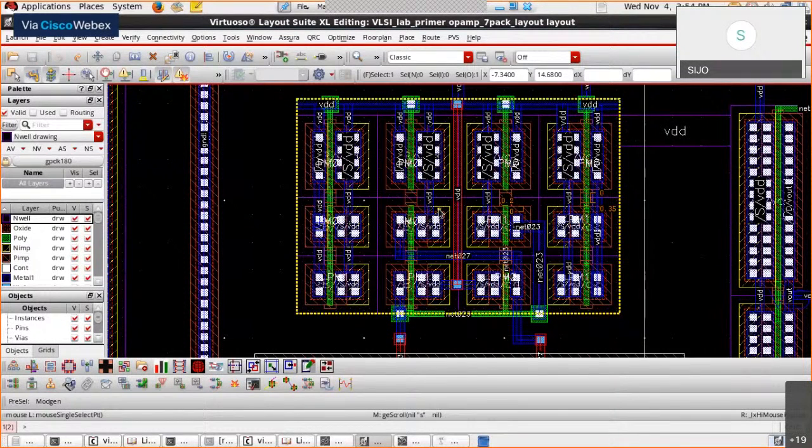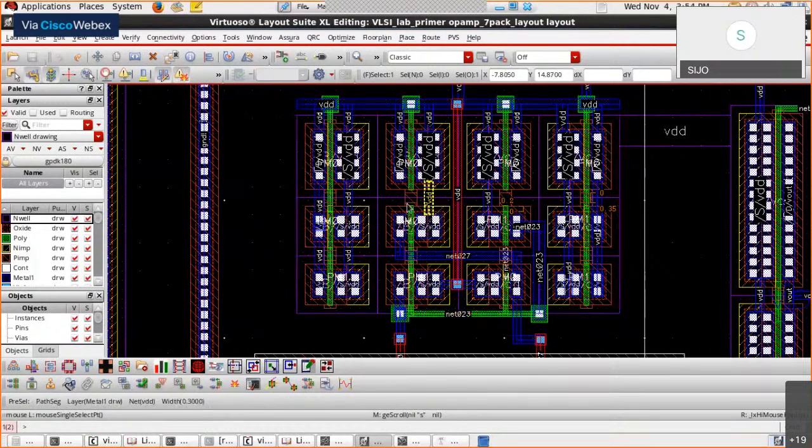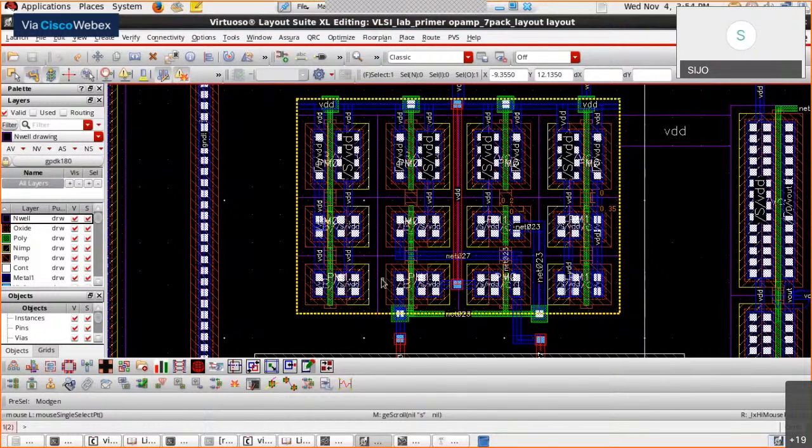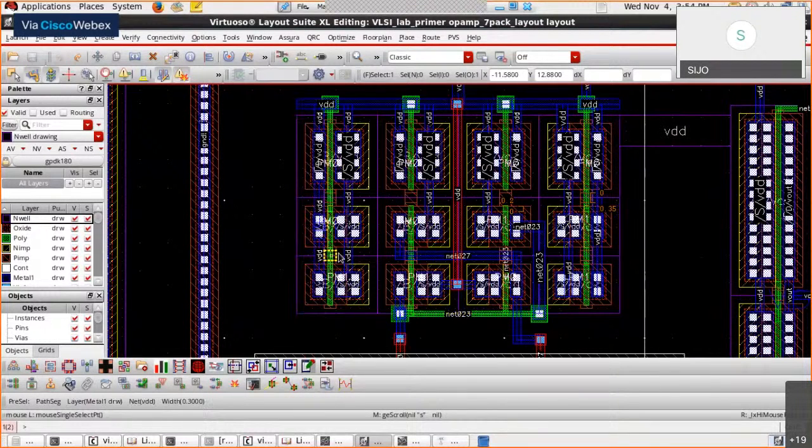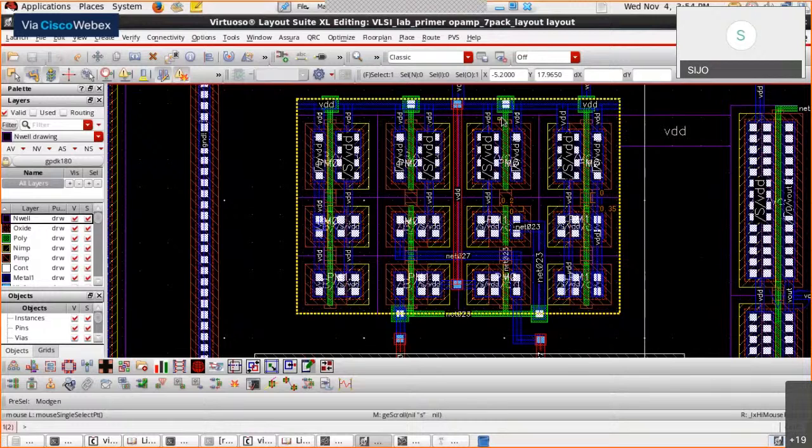But you can see there is a limitation. As I said, we can't put dummies everywhere, because that will end up with routing congestion. So in the bottom, you can see I have not added any dummies, but onto the left end column and the top row, you can see these are all dummies basically. So wherever it is possible, you use it. Also, in order to have a better aspect ratio, I have filled the vacant spaces also with dummies.